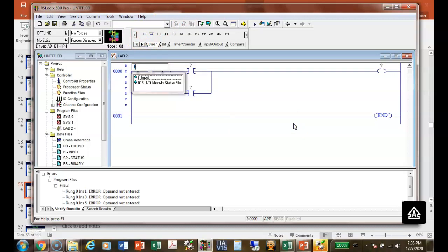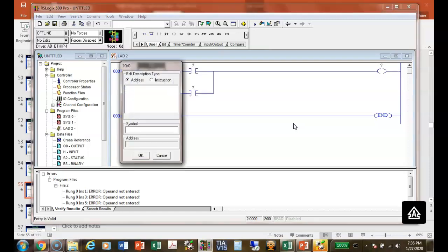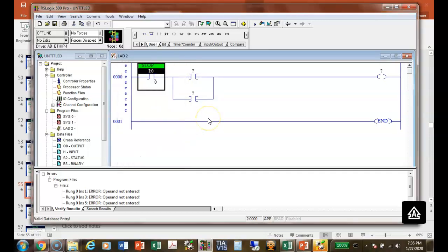So I'm going to assign it to an input, colon, right? These are internal ports, so they're going to be at slot 0. And then I have to select a bit. Everybody okay? Makes sense. Then I hit enter. Now it's asking me for a comment, and that's what it defaults to. Here's where you enter the symbol. Everybody okay? This makes sense?